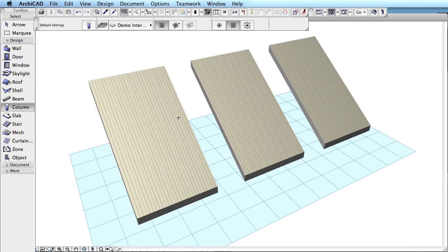Let's now see how we can change the orientation of the editing plane to help the creation and editing of elements located in sloping or inclined directions. Here you can see 3 roof planes in perspective view. We want to create an opening in the roof with given dimensions using different construction methods. First, we'll create an opening with given dimensions measured in the roof's plane.